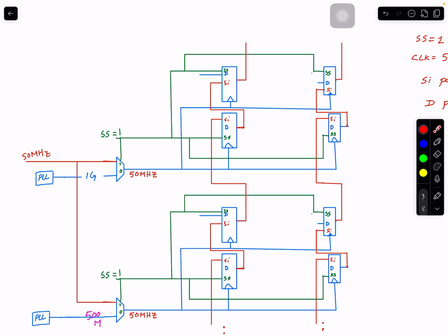But then you need to be careful about making sure these red parts are only on this 50 megahertz clock, and these other blue parts are on the other clocks. And wherever you see some crossing which is not valid, then you define set false path from this clock to this clock, or you give yourself an extra cycle, a multi-cycle path, because you want to give it a little bit more time. Okay, so you can live with that. Maybe that is possible.